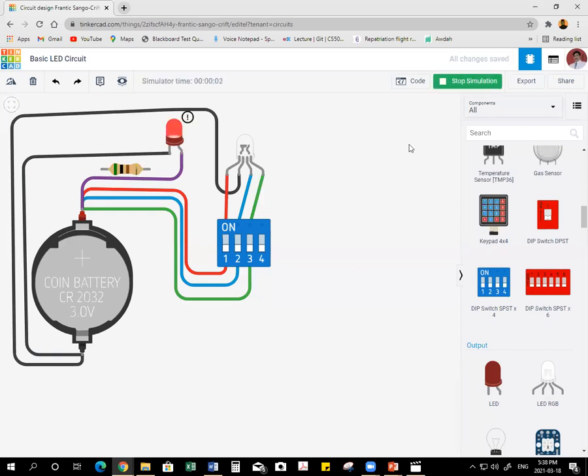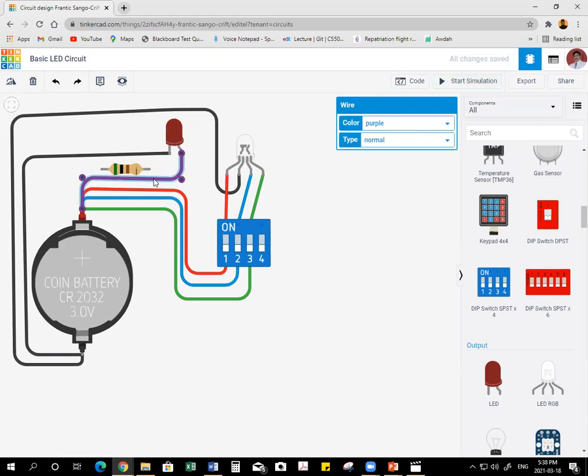now what you are seeing here is the normal LED directly connected to the 3 volts battery. How much is it? It is 61 milliamps. It can take only 20 milliamps as its capability. So for that we need a resistance in series with that. Okay. Before going to that, now we'll just stop the simulation and remove this.